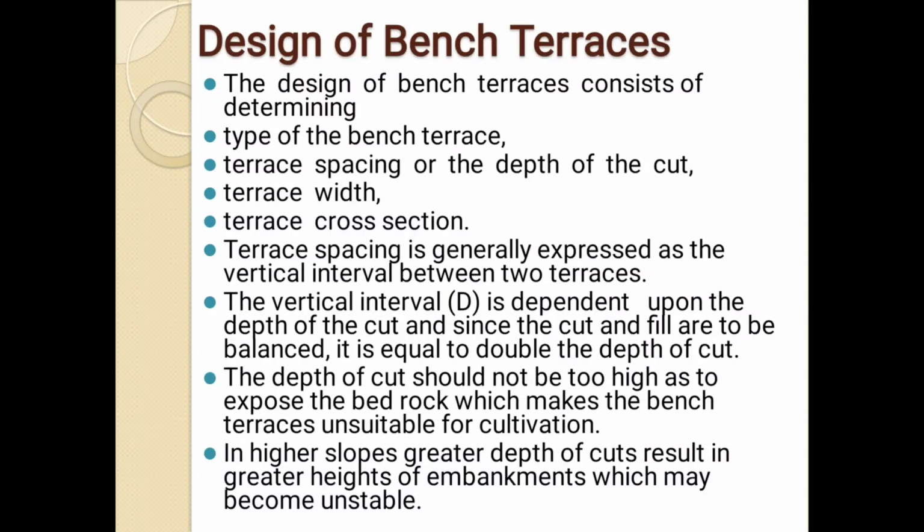First, while constructing a bench terrace, the design of bench terrace consists of determining the type of bench terrace, spacing, depth of the cut, terrace width, and terrace cross section. Terrace spacing is generally expressed as the vertical interval between two terraces. The vertical interval is dependent upon the depth of the cut, and since the cut and fill are to be balanced, it is equal to double the depth of the cut.